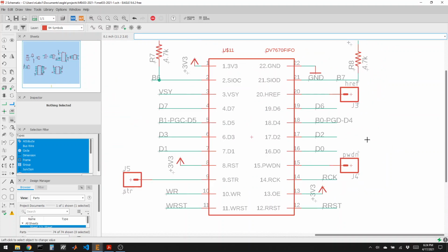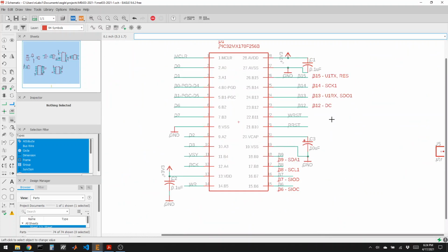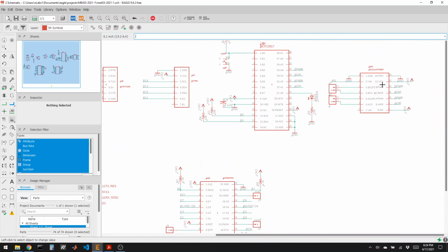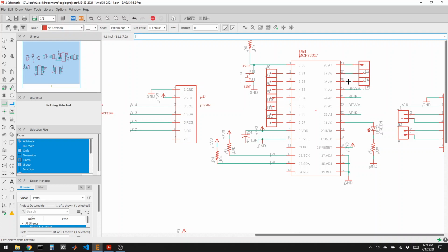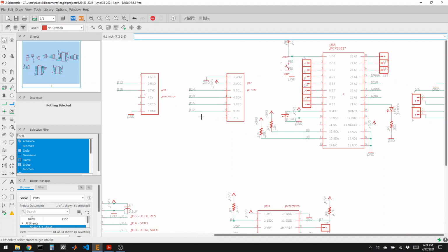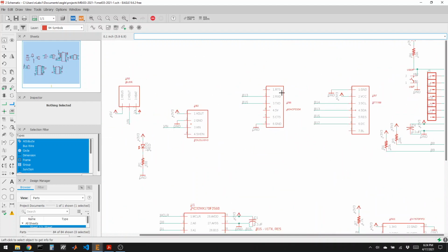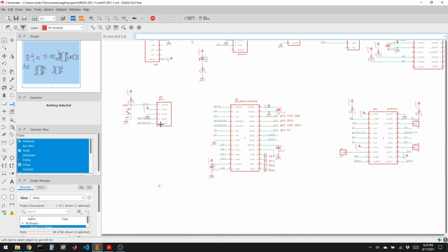Kind of like debug points. Okay, so look at that. The PIC, every pin is used. Some of them are used twice. Camera's hooked up, H-bridge is hooked up, the I/O expander hooked up, but some pins haven't been used. So all of those unused pins, we'll give them holes, just in case we change our mind later and want to use them. Okay, we've got our LCD screen and the USB to UART. We've got all our power. We've got the programmer.